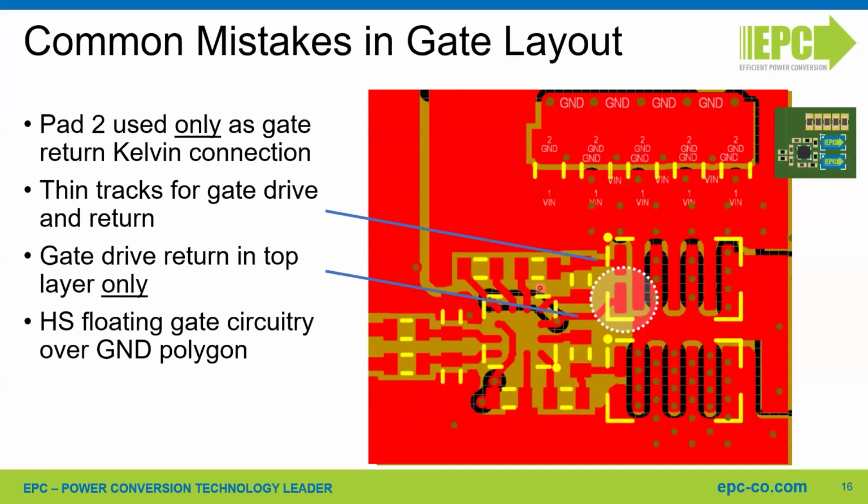The other effect, which is even more critical, especially with the smaller devices we have, is adding a significant amount of parasitic capacitance between the gate and the drain of the device. Let's not forget the ground is connected to the drain through the bypass capacitor.